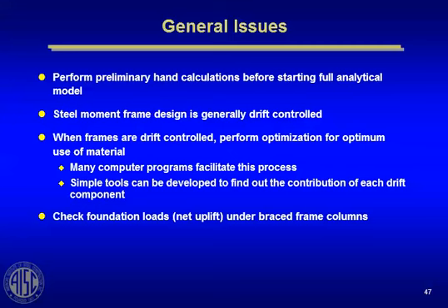Is the frame moving the way I think it should move? I think it's very important when you do a computer model to just put the wind loads on there and see if the frame deflects in a logical way. It's a good way to debug the model as well, to see if it's behaving intuitively like you think it should. These are some of the things that I think we as engineers need to do to be sure that our computer programs are giving us the answers that we think they are, and it's not the garbage in, garbage out problem.